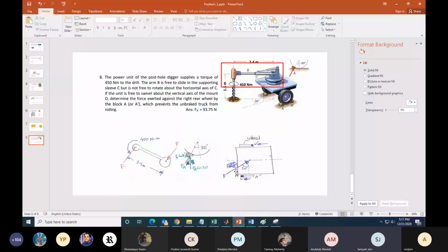Is the solution of problem number 8 wrong? The force that is acting on the square on the right side, that F force, shouldn't be there in the first place, because the force is already balanced when we are creating the couple. So I couldn't understand why there is a need of another force, which is now becoming unbalanced, because the cos component of the force is not being balanced, and the components F A sine 30 and F B sine 30 are cancelling each other. So there is no force which balances the sine component of F that is acting on the square body.